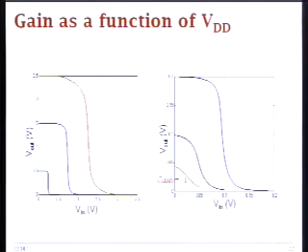If you apply 1.5 volt VDD, your VTC is still good. If you go even further down, let's say 0.5 volts, how about 0.5 volts? 0.5 volts is good enough to turn on a transistor, because you have a threshold of 0.4 for the PMOS, 0.43 for the NMOS, so it can still work.